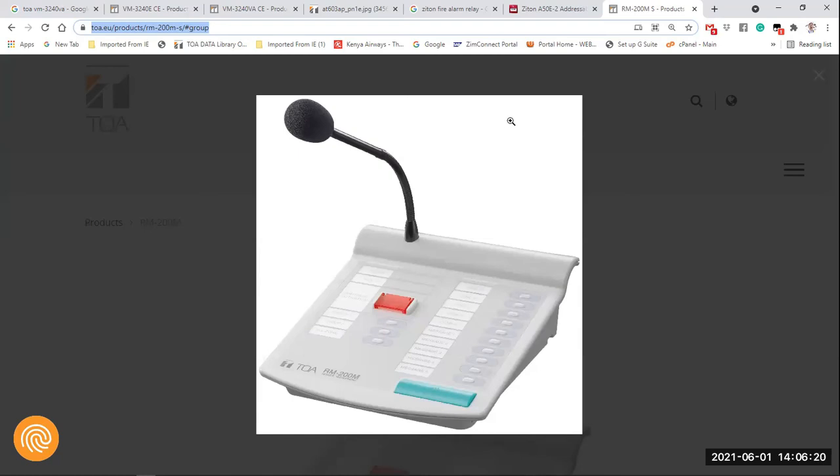Let's tackle them. The straight RM200MS that you're going to program, Emma, on site tomorrow, the left side does not work. The red button, the 3 associate buttons on your left-hand side where my mouse is, you can never program them. These do not work by default. So whether you want to try and evacuate people from here, they do not work. Okay. You can only program the right-hand side of the microphone. You cannot program the left-hand side.